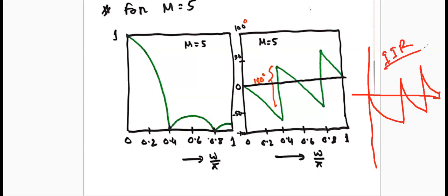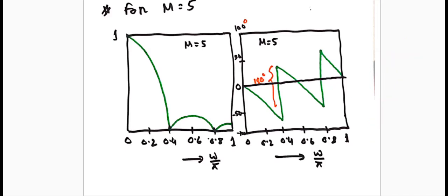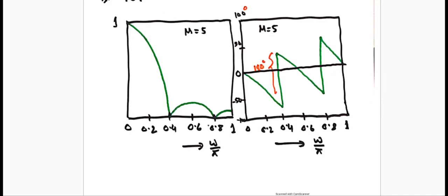In future, we'll discuss this nonlinearity. This is a great disadvantage of the IIR filter over the FIR filter. So that's why people are always choosing the FIR filter for precise filtration. With the IIR filter, it's not possible, or you can say it's difficult. You need another filter called an all-pass filter to rectify this problem.